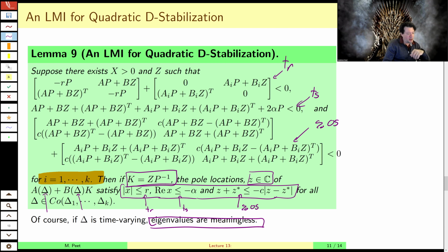But I would be relatively cautious, because really what you're doing here is mixing a representation condition for the eigenvalues of the representation with an LMI quadratic stability condition, and you're trying to extend that to system performance.